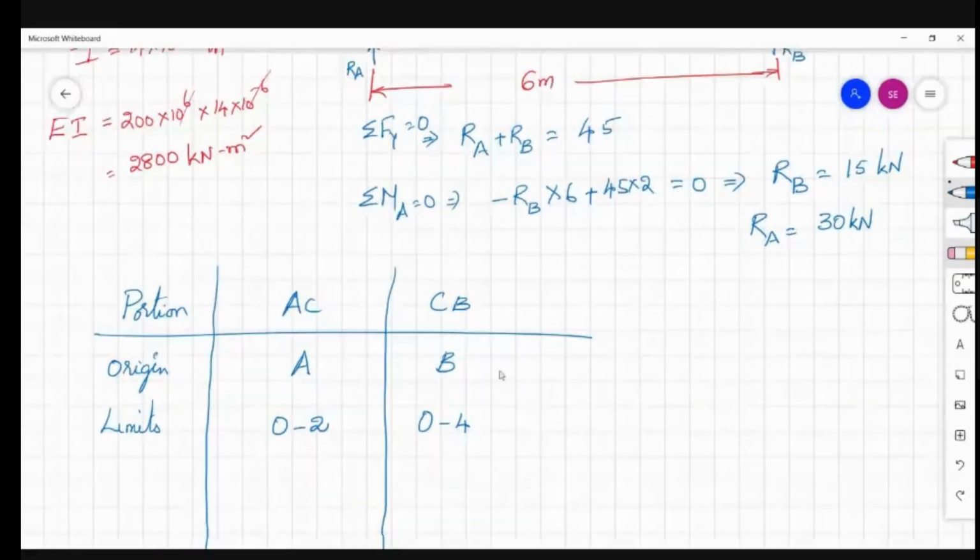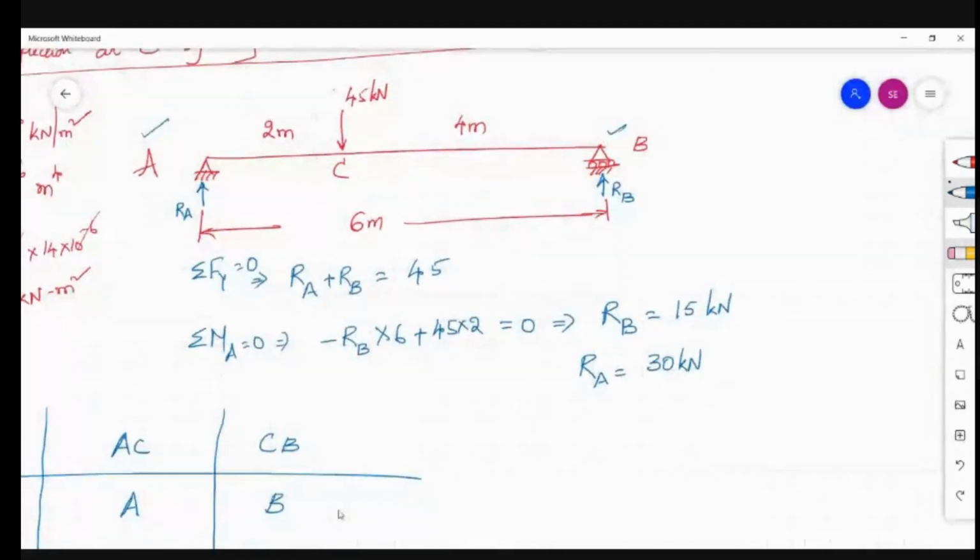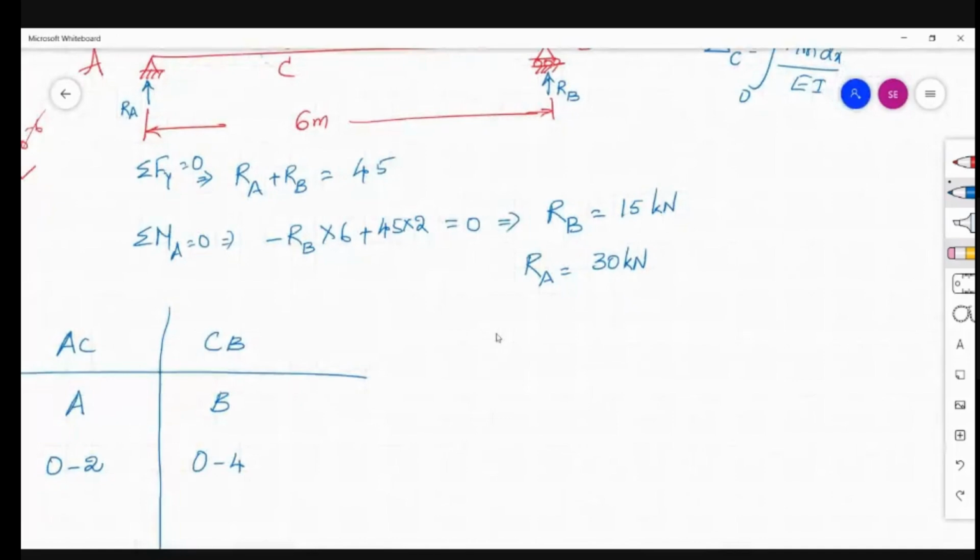Now just listen here. The deflection at any point under the load, delta C, as per the unit load method is the integral from 0 to L of M times small m dx by EI. Capital M is the moment due to the external load system at any section. Small m is the moment due to the applied unit load at the point where the deflection is required.